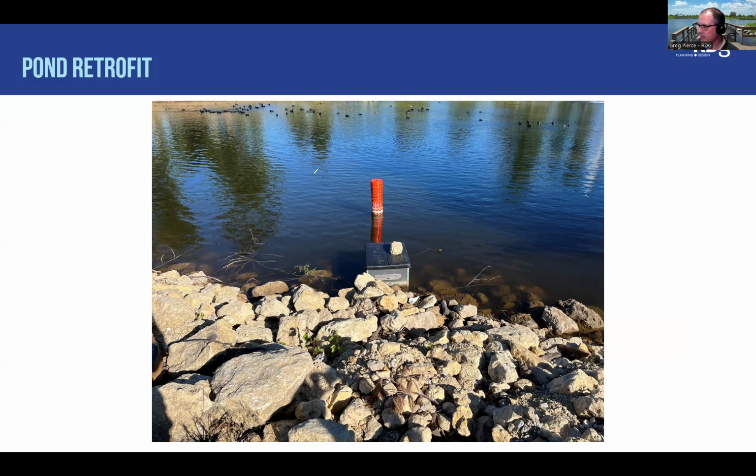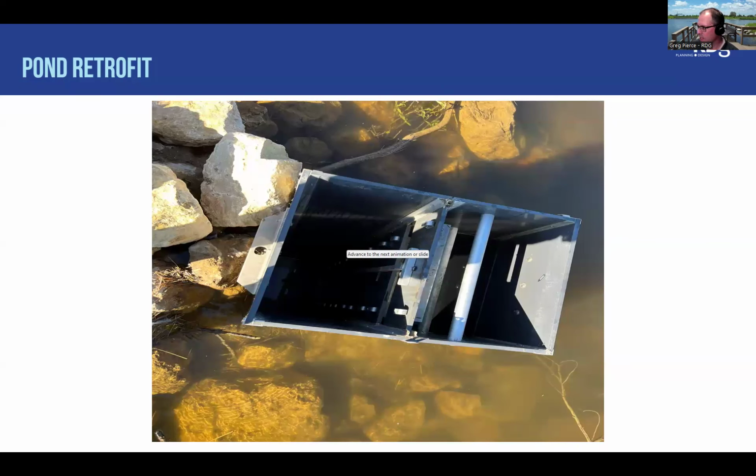We provided a kind of a low flow stage, so you can see the Hickenbottom. It's for trash. Then it goes into the water level control structure. This ties into a storm sewer that runs parallel to the pond over on this side. Here's what the inside of that AgriDrain water level control structure looks like. This little handle here is the actual operator that you can pull out and use to grab the little hooks on the stop logs and pull them in and out to manipulate the water level to whatever combination you want.